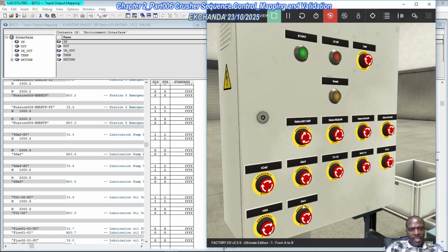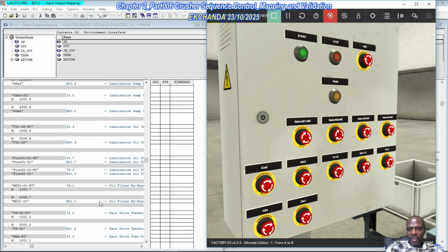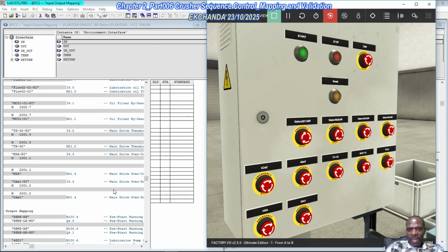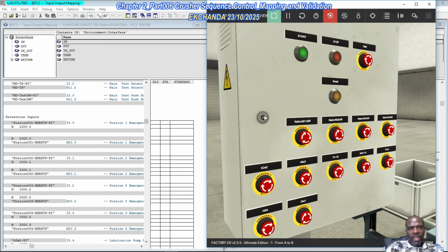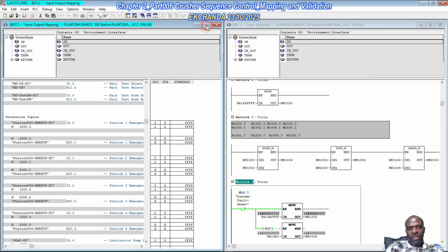Lastly, 2AE1 is the last man standing in this network. Right now it's okay. If we actuate this, the fault, emergency stop, normalize, it is still monitored as a fault. Do a reset, it clears. So basically we know how we can monitor all the system input variables.